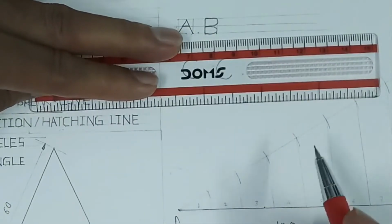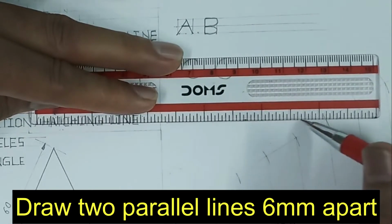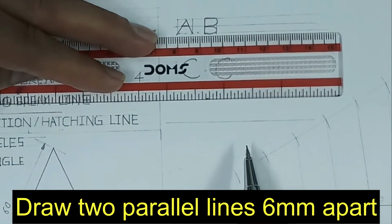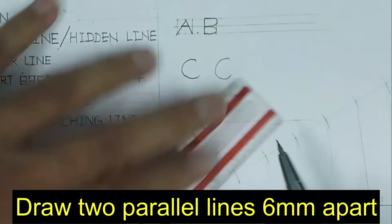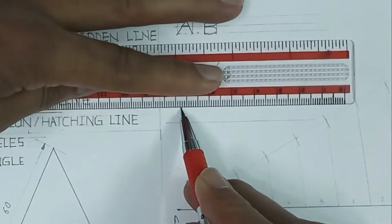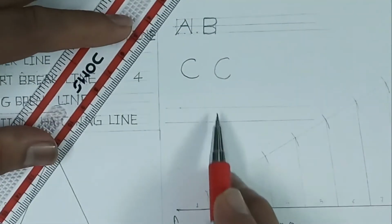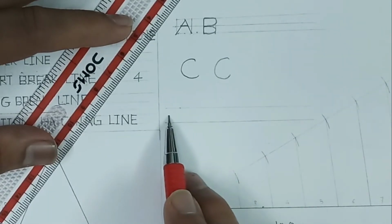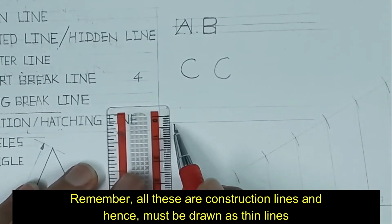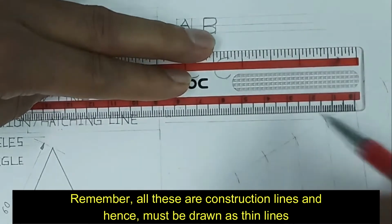Let us see how to draw these letters. As a representative, I will show you two or three letters. For drawing a letter, we first of all decide the height of the letter. In this case, I have taken height equal to 6 millimeter. So we draw two lines 6 millimeter apart, drawn as thin lines. Then draw another line halfway between these two, that is at a distance of 3 millimeter from either top or bottom. This is the way the middle line is drawn.